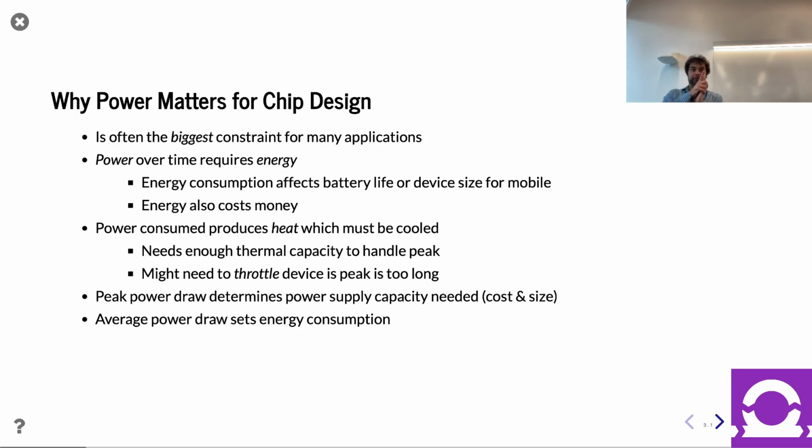What's interesting, I'm going to finish this thought and take another question. There are scenarios, not just with data centers, but also supercomputers, where they have to do funny things to not break the grid. So if you're a really, really big data center or a really big supercomputer, you're burning megawatts, maybe even tens of megawatts. To suddenly take that much load on or off the grid, most grid operators cannot handle that, right? That's not what they're designed to handle. They can't just take 2 megawatts going on or off.